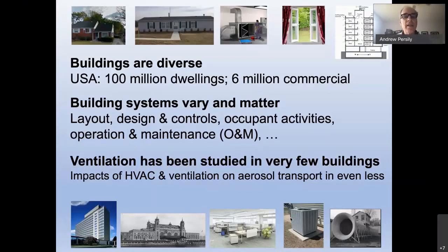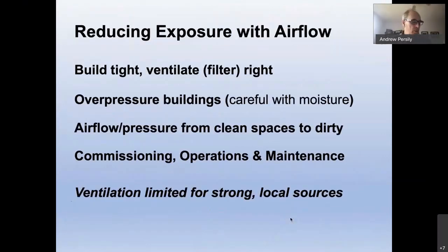And then the number of buildings where we've studied the impact of ventilation on aerosol transport is even smaller. So what can you do with airflow to reduce aerosol exposure? And this slide, I originally created it with respect to outdoor aerosols. The first thing you can do is build the building tight and ventilate it right.